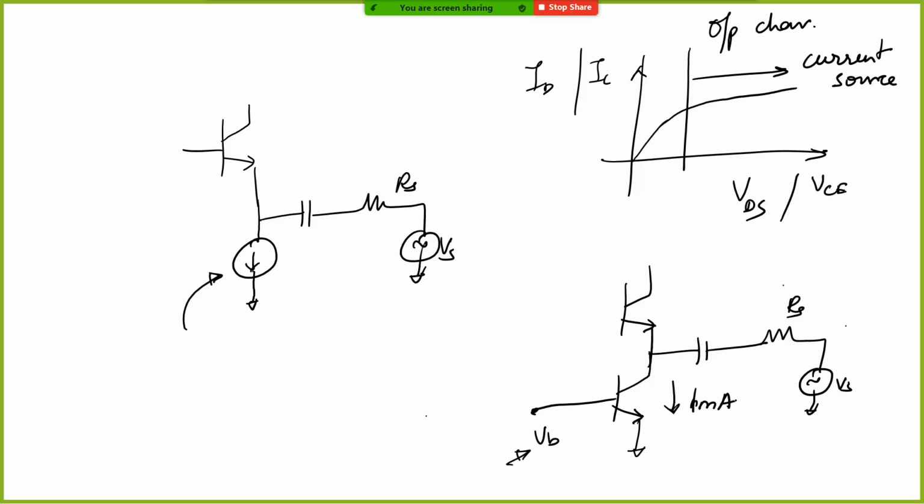Okay, and that current gets copied over to multiple circuits which might be in your board or your breadboard or whatever. Okay. So basically the way in which it is typically done is you have one reference current which is given. So you do a lot of things to make sure that it is very stable across temperature and other things, right? And then you need to copy this current. So you need to copy it to multiple instances in your circuit where you need this current source. Let's say you have 5 current sources which are needed in your circuit. So you need to have a way of copying.